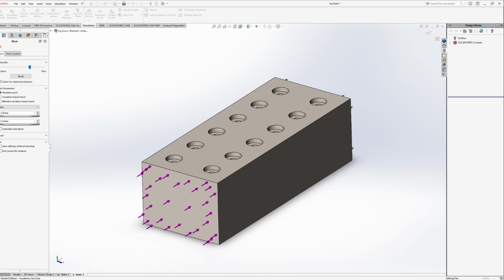So don't be alarmed. What'll happen is you'll get a little pop-up. It'll show you the processing power required to finish it. If it is taking too long to do, just create a coarser mesh. And that'll actually be good if it does take a bit too much time, because that just means that between what I do and what you do, we might be able to compare results. Obviously, I can just create another static simulation and compare results with my own varying mesh, but it could be something interesting if we want to do that.